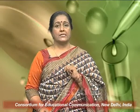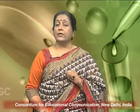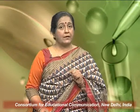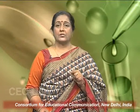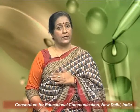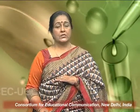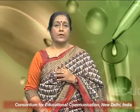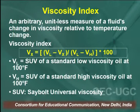In the case of lubricants, viscosity depends upon the temperature. It tends to decrease with increase in temperature. Viscosity index may be regarded as the average decrease in viscosity per degree rise of temperature between 100 degrees Fahrenheit and 210 degrees Fahrenheit. The variation of viscosity of an oil with temperature is given by the viscosity index. So, viscosity index is a unitless measure of a fluid's change in viscosity relative to a temperature change,